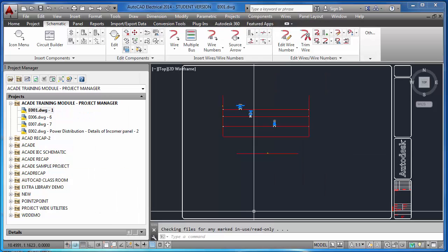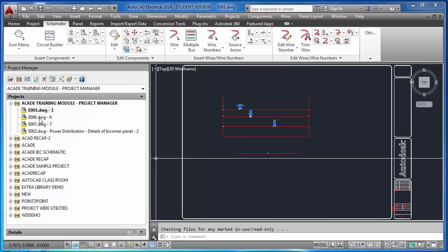If you give only the file name, like E0006, maybe while making the drawings you may be quite sure what is there in this particular sheet, but after some time, or when an unknown person opens this drawing, he cannot understand what is there in this particular sheet. So better add some descriptions to each sheet.